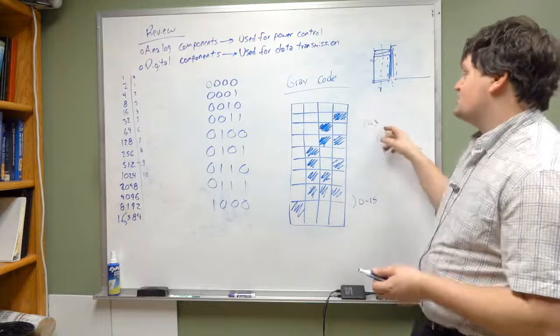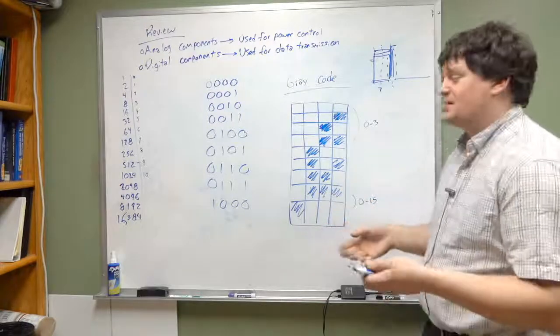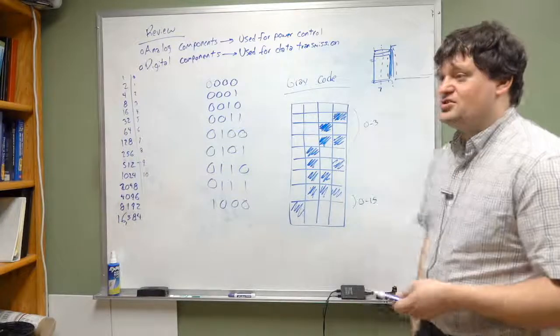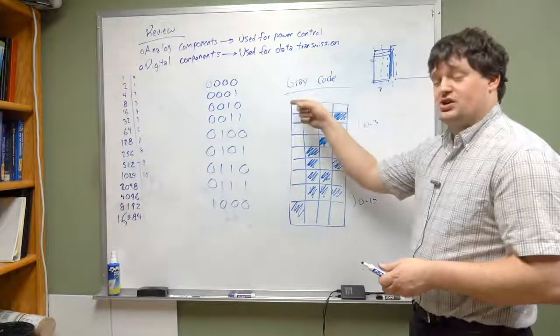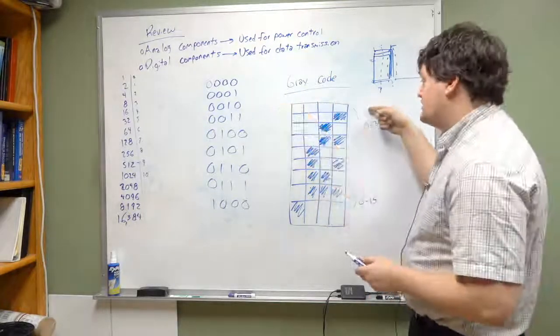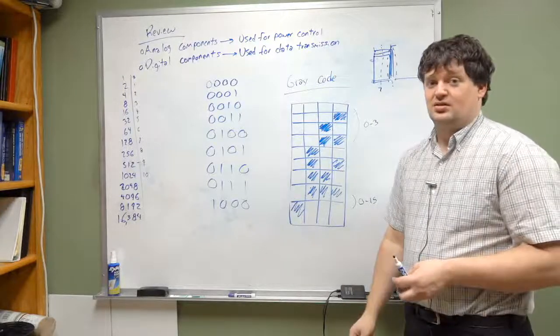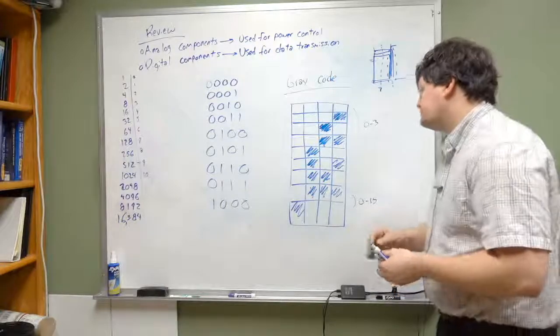This right here, the transition 0 to 3, that's not a huge difference. If it reads a 0 or it accidentally reads a 3, that's great. This transition here, there's no difference at all. If there is an error, it accidentally reads the value it just was, or maybe it accidentally reads the value that it's going to be. But that's it. That's the only change.